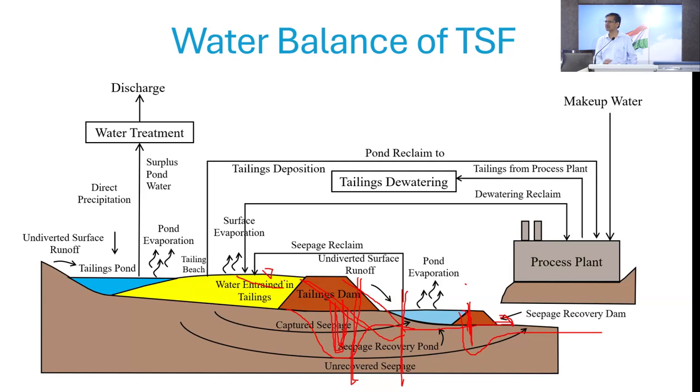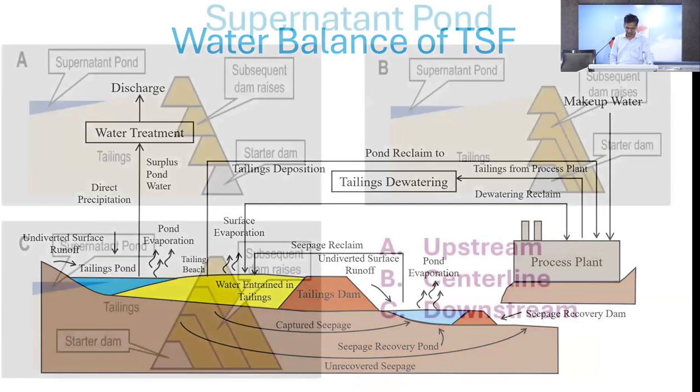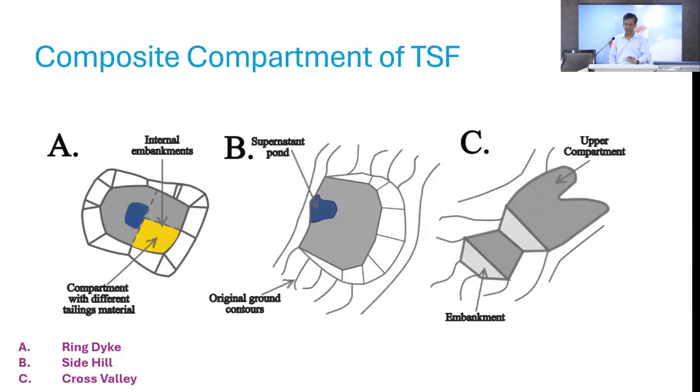So that way I could know that the geomembrane they have provided is still working. Otherwise, outside from the side it has been exposed. So I think you can better tell how to protect them now, because after 10-11 years it has been exposed. It is not covered from the side. Inside I could not see it, so my job was just to check whether there is seepage, and accordingly try to draw the phreatic line to see whether it is going that way or not. So the geomembrane works, but this aspect also needs to be considered when I am talking about a geomembrane liner.